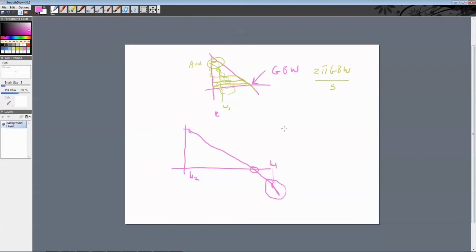But we could have one pole at 1 radian per second, and another pole at 10 gigaradians per second, plus A_V beta, and I'm just going to put 10G here. Then I have A_V times 10G, and this is the Q(s), not H(s).